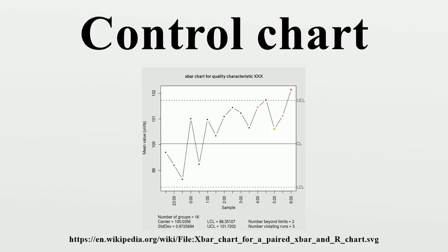Shewhart created the basis for the control chart and the concept of a state of statistical control by carefully designed experiments. While Shewhart drew from pure mathematical statistical theories, he understood that data from physical processes typically produce a normal distribution curve. He discovered that observed variation in manufacturing data did not always behave the same way as data in nature. Shewhart concluded that while every process displays variation, some processes display controlled variation that is natural to the process, while others display uncontrolled variation that is not present in the process causal system at all times.